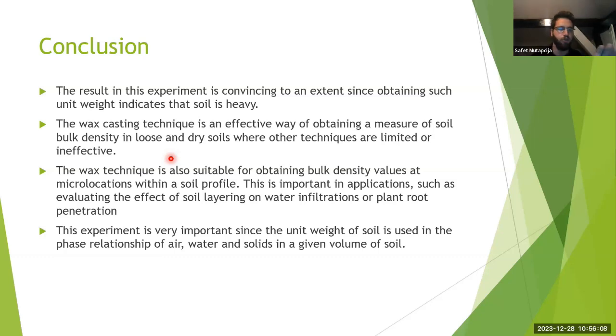And the project is going to define the modulus of elasticity of that embankment. For the pipes, it is 30 megapascals of the dynamic one. So there is one dynamic test with one weight, dropped from like 1 meter high. Based on that, you're going to calculate your modulus of deformation.